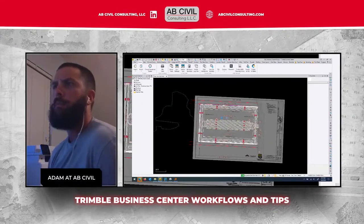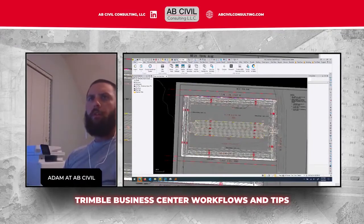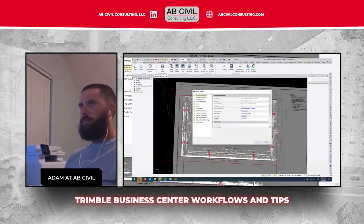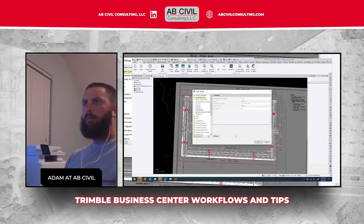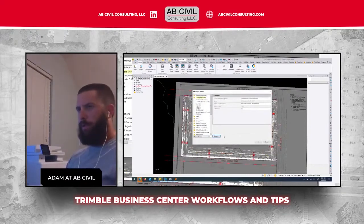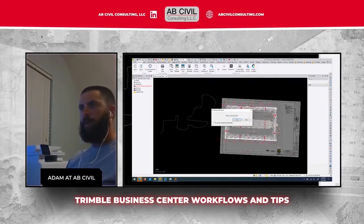So what I can do here, if you go up to Settings, Project Settings at the top, you go to Coordinate System, hit Change. I think this is Washington State North. I don't like to put this coordinate system in here because it's going to write a calibration file, or a type of calibration file, when you export. So I'm not going to save this. There's some issues with it.